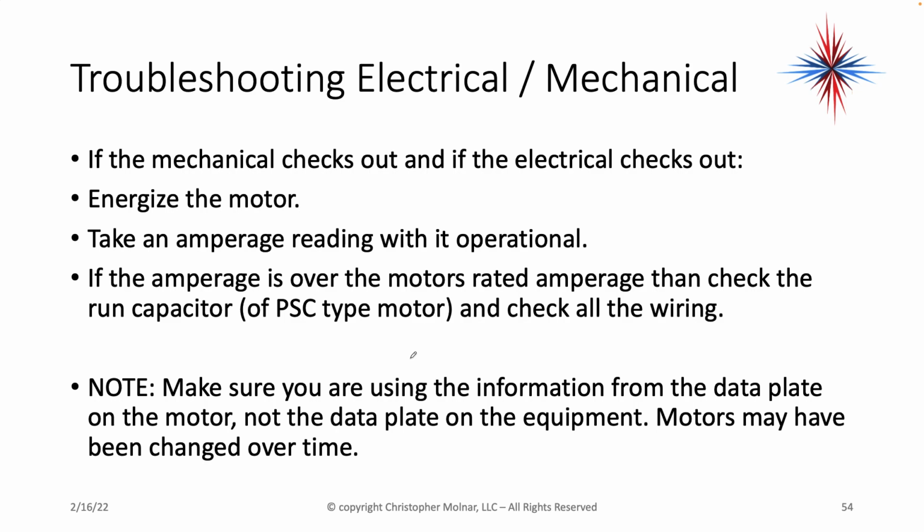Make sure you're using the information to compare with from the data plate on the motor, not the data plate on the equipment. Motors may have been changed over time, and you might have a different motor than what was in there originally. I've seen it happen on more than one occasion.